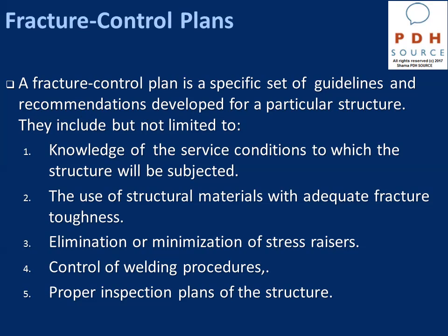For example, for bridge structures we may use intermediate loading, and for machine foundations that are exposed to cyclic dynamic load, we may have to use a dynamic loading rate, not a slow loading rate.